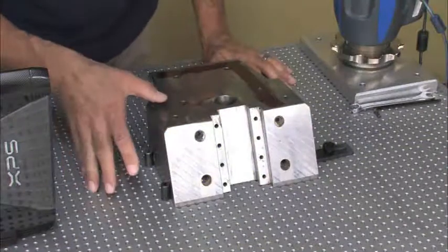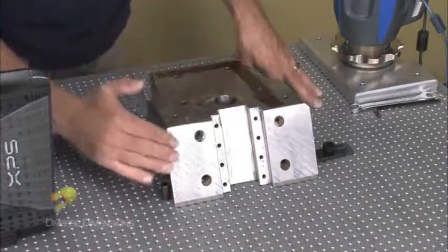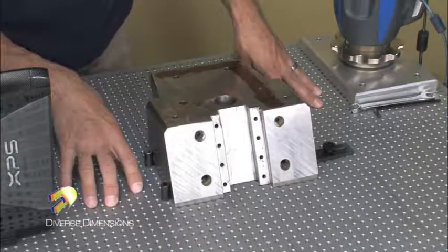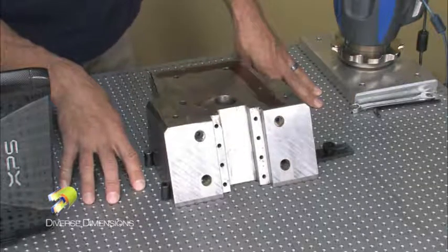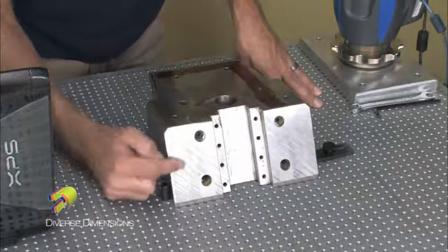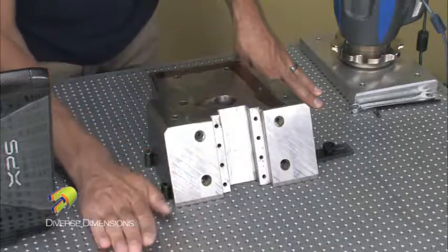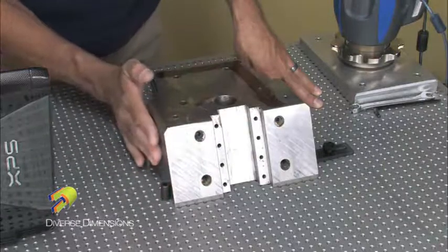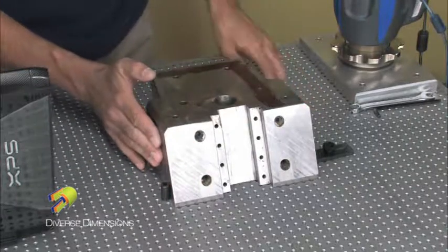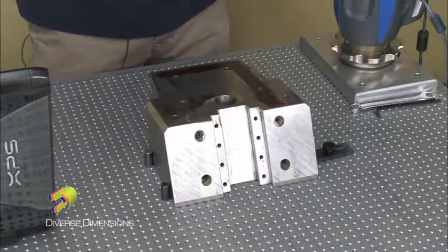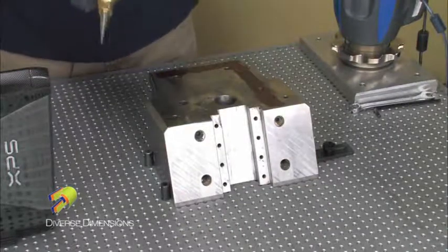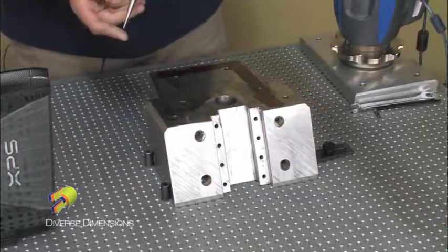Now I've got my block positioned on the table here, so I've got this side exposed as well as this side here, and then the bottom face is right up against the table here. So what I'd like to do is construct the coordinate system that's going to be between this plane here, and then this side here. And I've got my Quantum today. I've got my 1 millimeter probe on here because some of the detail that's on the back side of this needs to be tracked with a 1 mil probe.